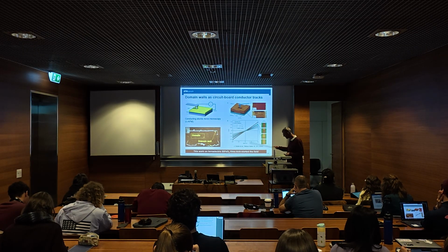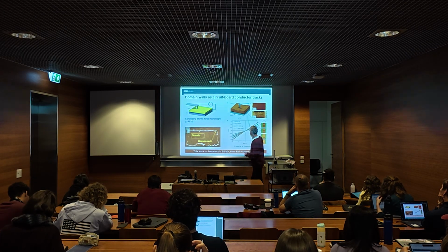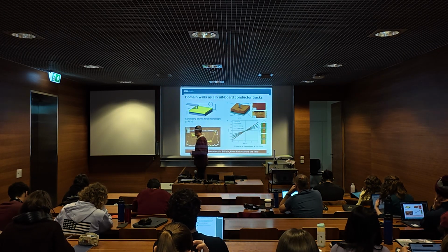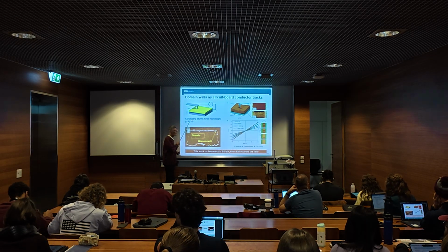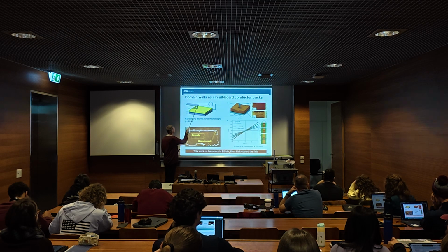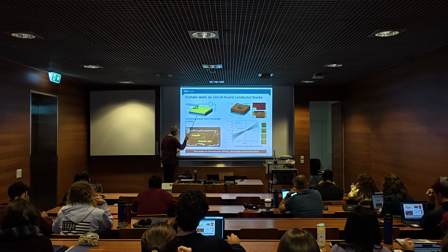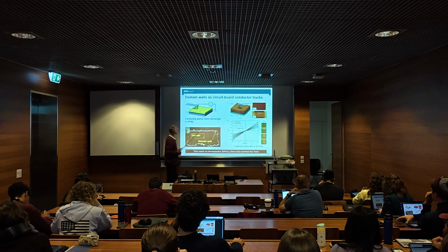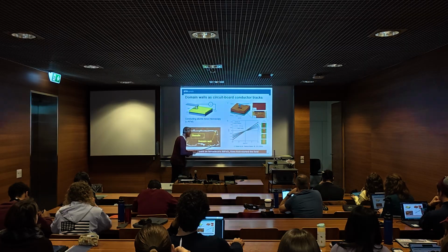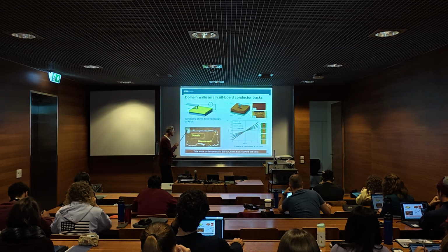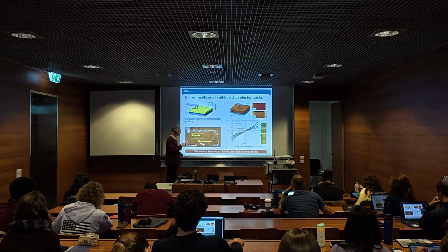This is the experiment that kicked it all off in 2009. Bismuth ferrite, which is a ferroelectric material, and then they did conducting atomic force microscopy. Now you know what that is. So they moved the tip across the surface and they measured the electrical current going from the tip through the sample and into a back electrode. And then they measured where there are domain walls, you suddenly have a lot more conduction, here shown by the brighter region. So that was the paper when they realized, oh yeah, they can be like wires.